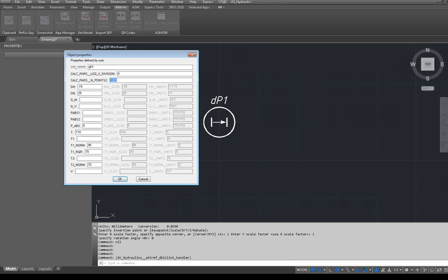Calc parse endpoints. This is important parameter for calculation setup. When you perform complex calculations, you want to get good tolerance. To improve calculation tolerance, you increase number of points for calculation. And the main parameter of differential pressure source is dH, or its differential pressure. The more is differential pressure, the more is flow in your scheme.